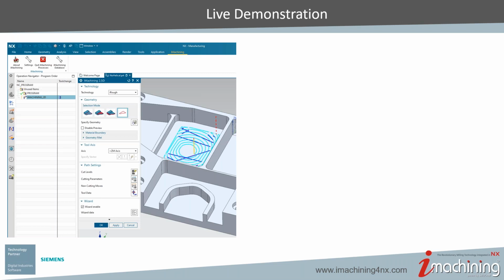There is a what's new that actually goes over all the individual features, because there are so many more little features that have been added all over the place. I mean, 3D iMachining, you can limit the cutting to 1 ACP. In iMachining 3D, we automatically change the cutting angle on every depth of cut. So when the tool is stepping up, we increase the engagement angle to have the same cutting forces and to have more efficiency. If you look at the what's new for SolidCAM iMachining 2021, it's huge. I forget how many pages it is, but I'm sure it's 40 or 50 pages.